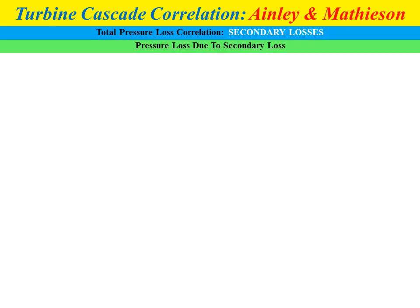Okay, for turbine cascade correlations introduced by Ainley and also Mathieson, there are a few other correlations based on different types of losses. Previously, the total pressure loss correlation that we already discussed, introduced by Ainley and Mathieson, is based on the profile losses. However, Ainley and Mathieson also introduced a total pressure loss correlation based on the secondary losses. From the correlation we will get the pressure loss due to secondary loss for the turbine.